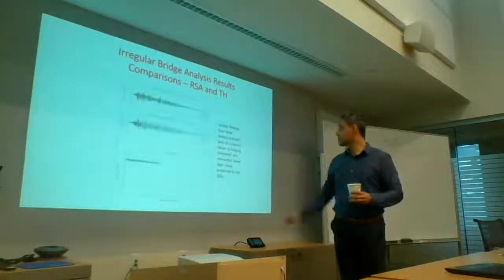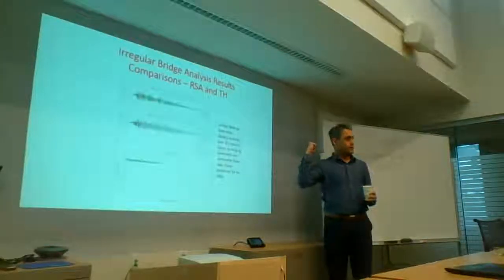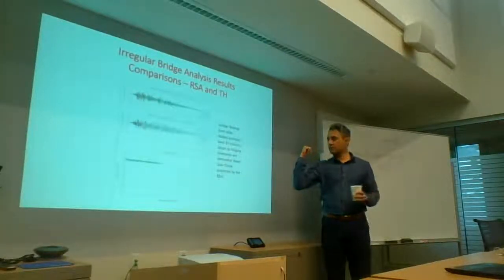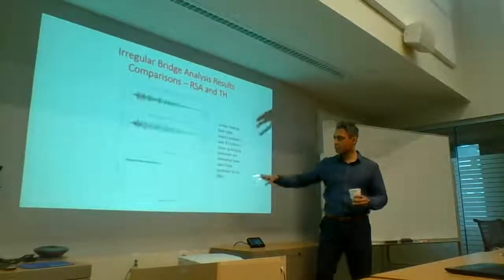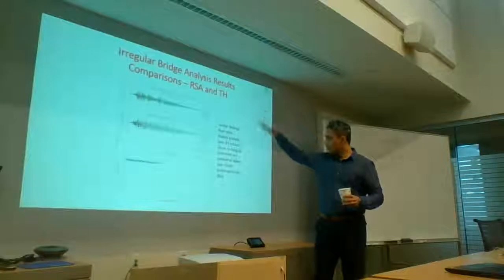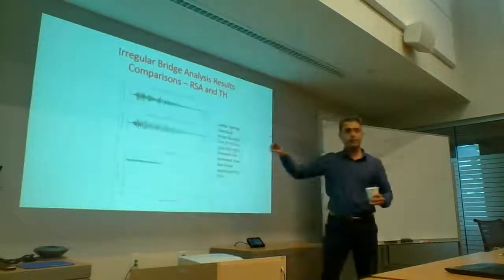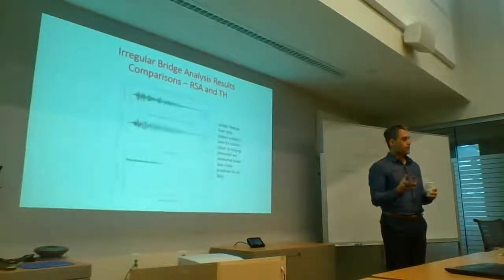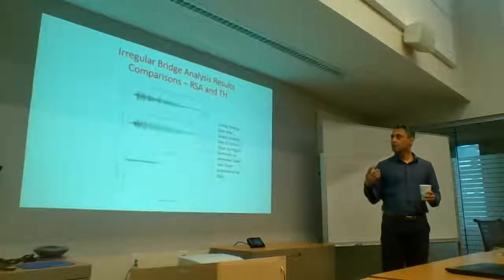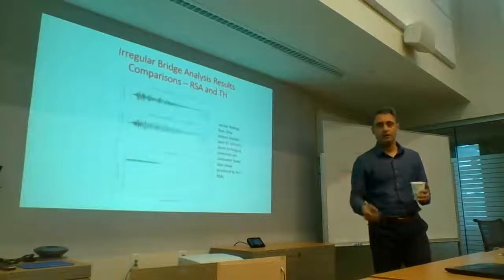And here you see B11, which was a little bit over from the elastic dynamic analysis or response spectrum analysis. It was giving us about 10 to 30% overstress. It's still the highest when we run the time history, but it's just inside the PM curve. So the nonlinear time history analysis has given us a better result, in that because this is capturing everything in real time, we can demonstrate that we're okay.